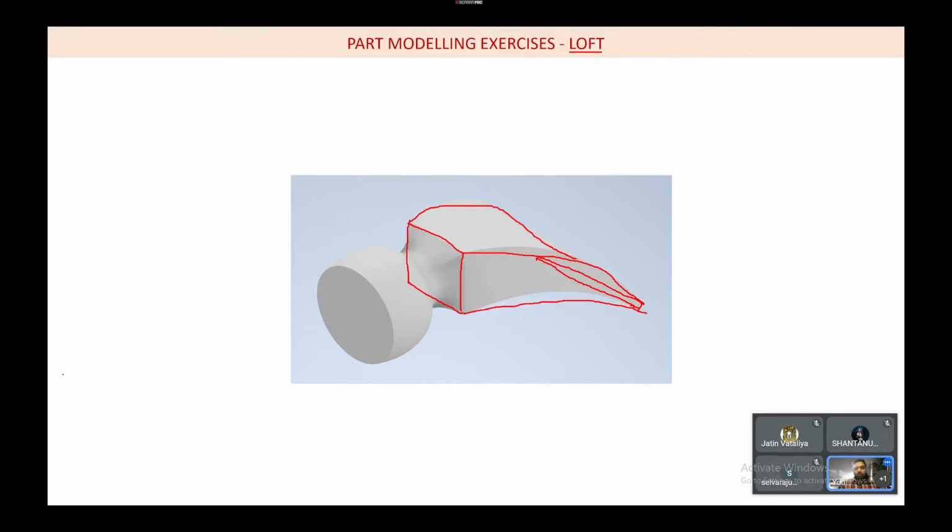So what I have done is, I first created a plane and I created the edge on that plane, and the new plane, how I am going to orient it is, it is going to be inclined at an angle of 45 degrees to this plane and it passes through the edge. So the option to do that is angle to the plane around edge. What it does is, it creates an angled work plane around the face or edge. Okay, so this is the thing.